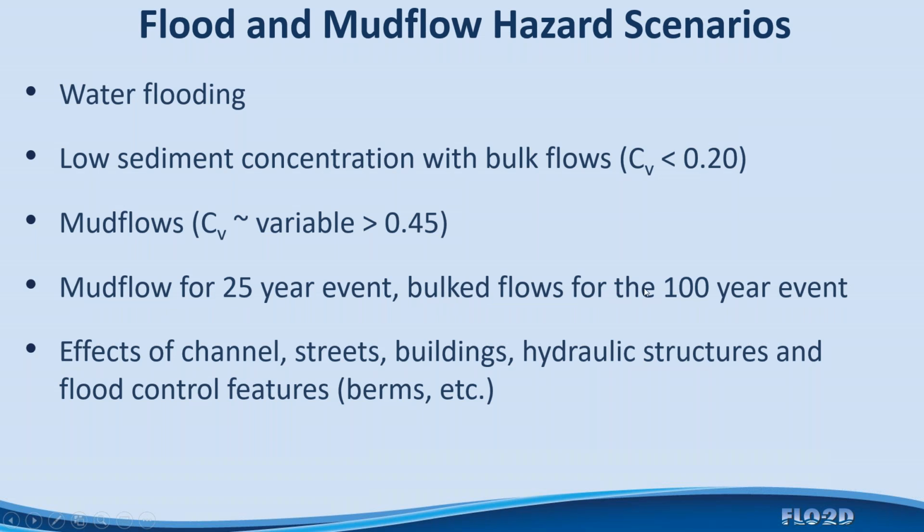Typically, in order to have a 100-year event that might generate a mud flow, it's going to be completely a landslide event that's going to come through onto your fan. And so I suggest that you remember that and recognize that your mud flows typically will occur for a 10 or 25-year hydrologic event, and that if it's a higher or less frequent event, higher magnitude, with more water volume, it's going to be more diluted and more on the order of a mud flood or just a low sediment concentration flooding event.